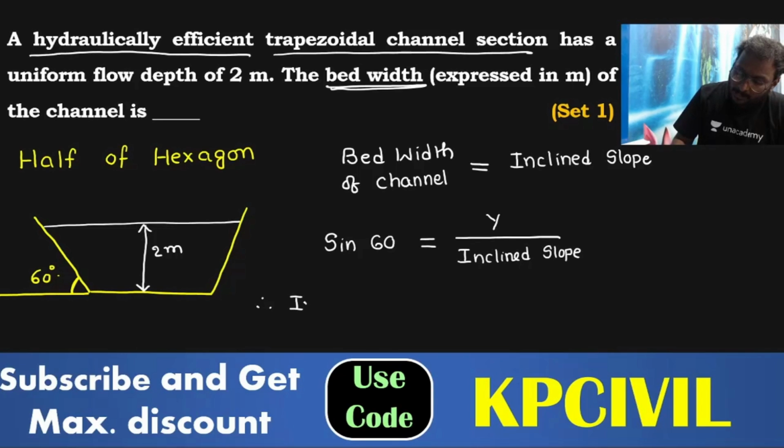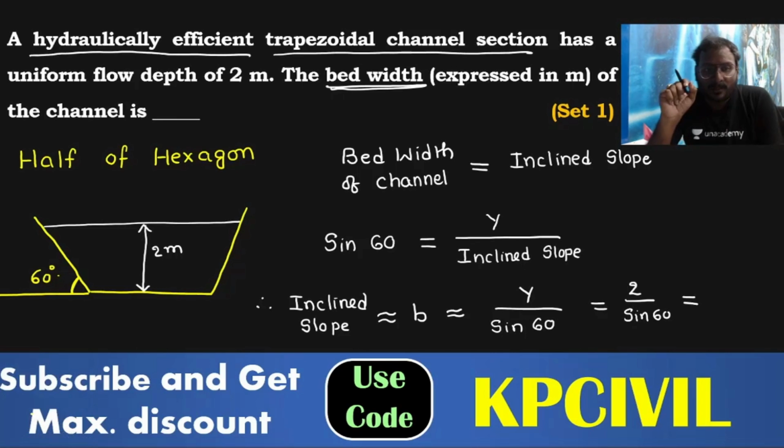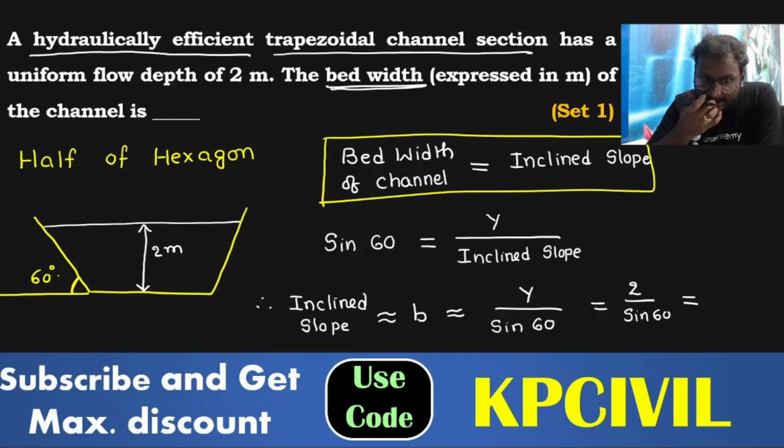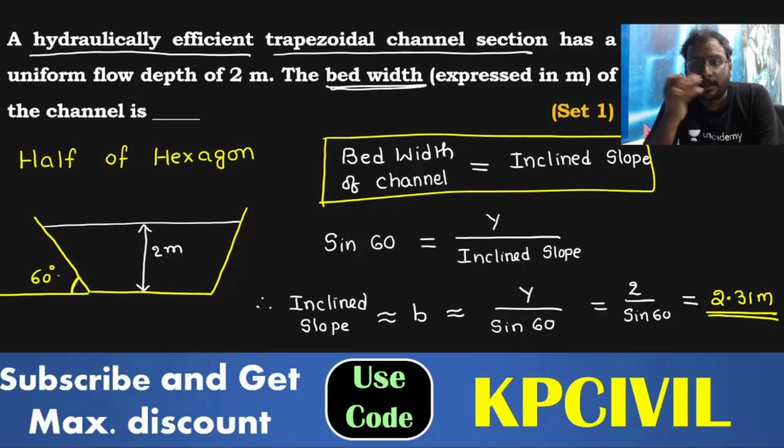So what can I write now? Inclined slope and bed width are both the same. Inclined slope is equal to bed width is equal to y by sin 60. Y is equal to 2, divided by sin 60. Simple question: 2 by sin 60. The only point you need to know is that a hydraulically efficient trapezoidal channel section is half of a hexagon, sin 60 is equal to y by inclined slope, and very importantly, inclined slope is equal to bed width. 2 by sin 60 gives 2.31 meter. Very simple.